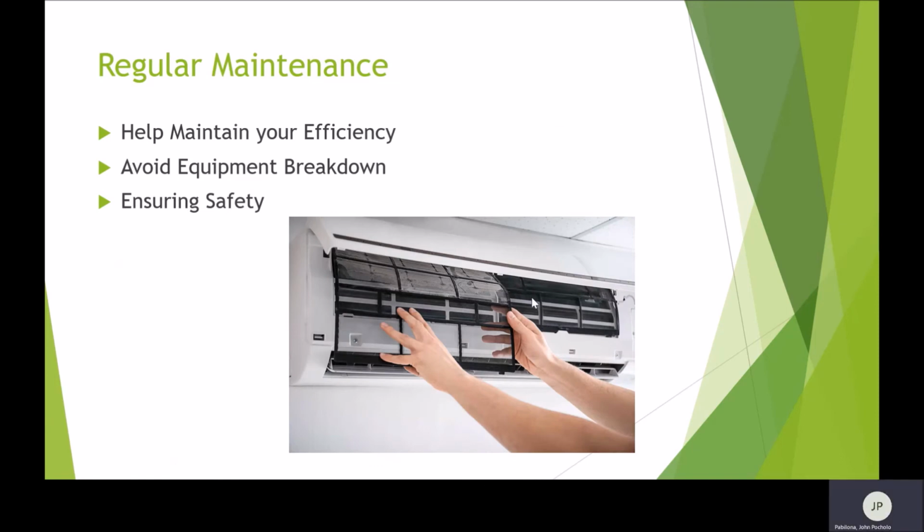And lastly, para doon sa ating mga energy efficiency approach, meron tayong regular maintenance. So, regular maintenance can help you maintain your energy efficiency kasi nagkakaroon tayo ng dirt accumulation lalo na sa mga air conditioning units, sa blowers and fans, doon sa mga filters niya. So, pag madumi na, lalong mahihirapan yung motor natin or mas mag-draw siya ng higher input para i-push yung hangin pabalik sa ating system.